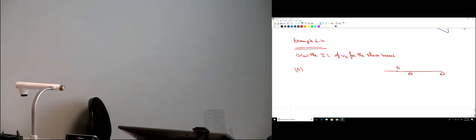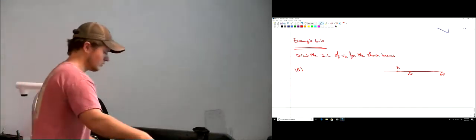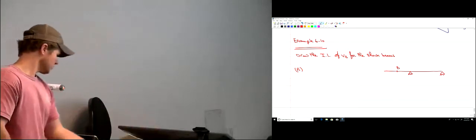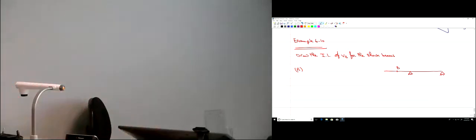So you either plot them member by member so that the graph shows the value. But if you just plot the envelope of, let's say, the bending moment diagram, it doesn't show the value. So you can plot this for the entire frame and then write the values by hand, so you just have one figure for the entire frame. But you're going to have to tag the value of the bending moment at the critical points, the start, the end, the middle of each member, okay? And just label them.